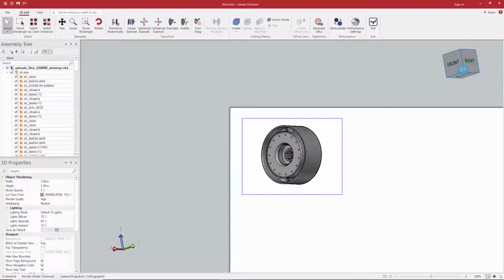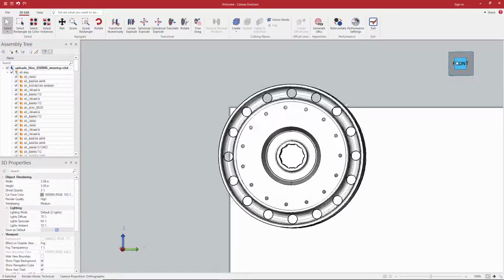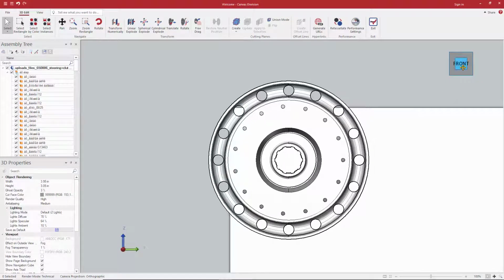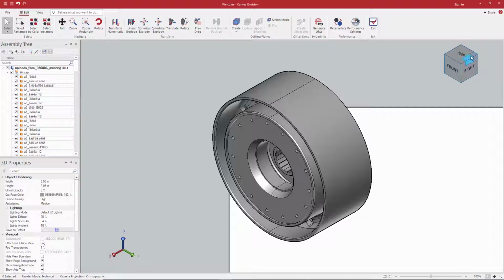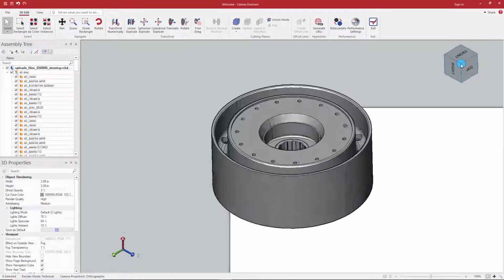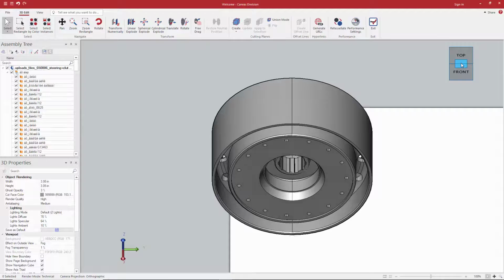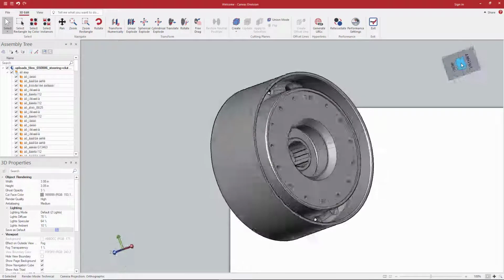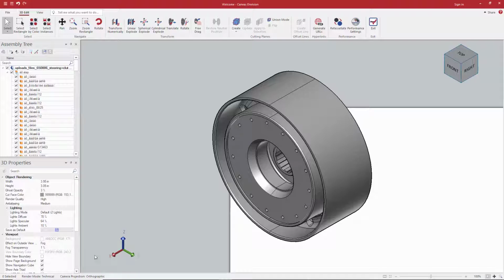It lets me click on any of its surfaces, and it will turn to the orientation of the model like so. I can also click on any corner to see an orthographic view of my model, and also click on any edge for an angle view. If I click multiple times on any edge, corner, or face, it will rotate the model 90 degrees to the right. The Navigation Triad is located down here, and it represents the direction of the model based on its axis.